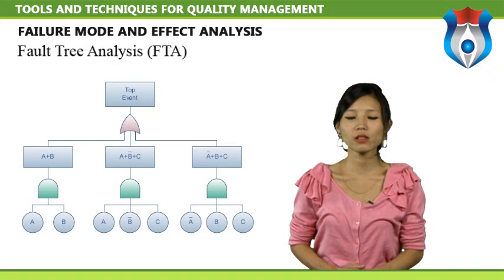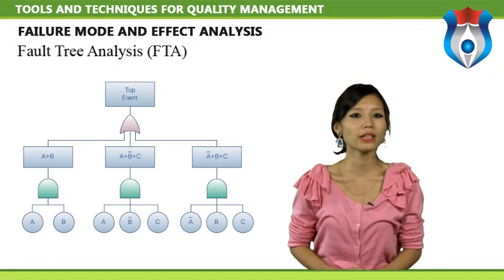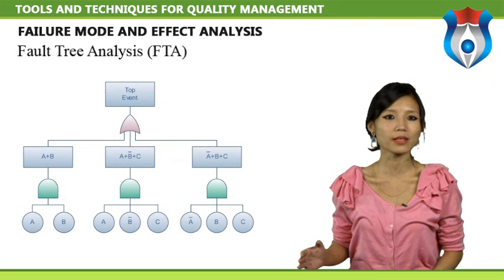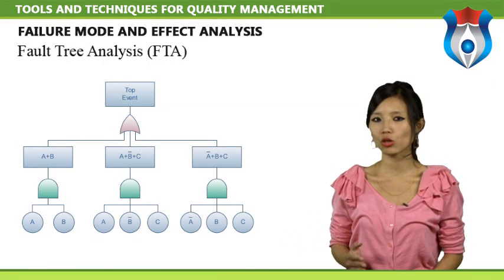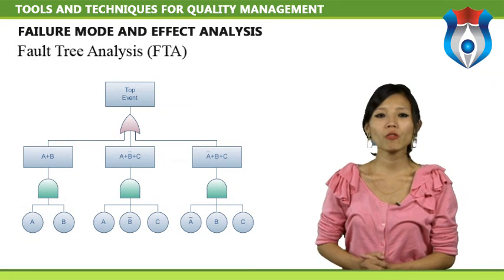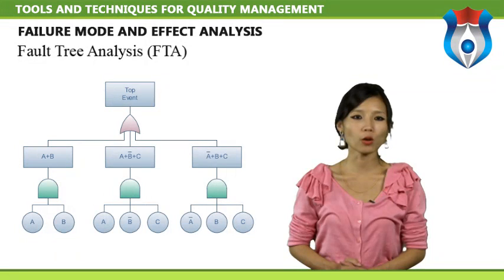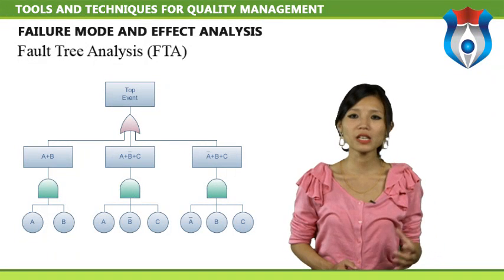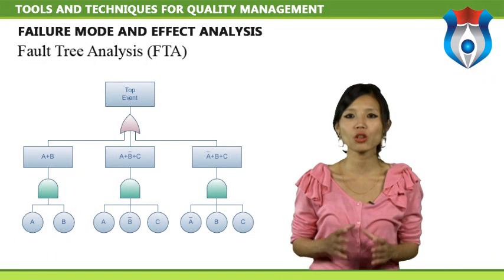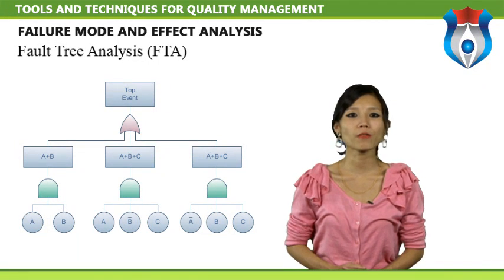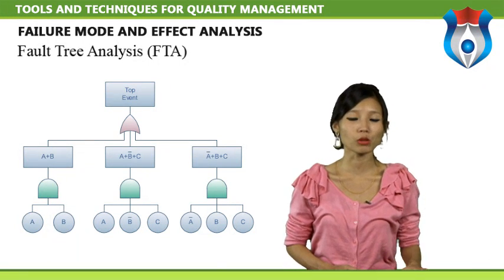Fault tree analysis (FTA). A fault tree analysis (FTA) is a deductive top-down method of analyzing system design and performance and is sometimes used in QRA. It involves specifying a top event to analyze, such as a fire, followed by identifying all of the associated elements in the system that could cause the top event to occur. Fault trees provide a convenient symbolic representation of the combination of events resulting in the occurrence of the top event. Events and gates in fault tree analysis are represented by symbols.